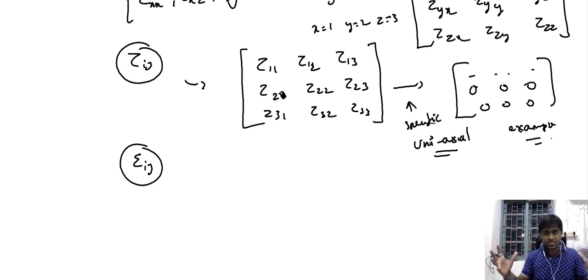So this is the generalized setting that we can consider, and for that generalized setting, the stress is expressed as a tensor. And if we want to narrow it down to a specific case of uniaxial tensile load that is acting on a perpendicular plane, then all these other entities will turn out to be 0, and only one non-zero entity would be present. So from the generalized expression, we have now arrived at a specific representation for the stress. So the stress as a tensor would help us describe the mechanical condition in a most